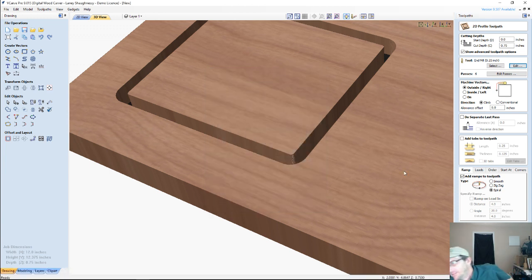Thank you, Bob, for pointing that out. So, with spiral ramps, you want to make your feed rate match your plunge rate. Sorry, your plunge rate match your feed rate. All other ramps and zigzags and things like that, you don't. You just leave it as is.